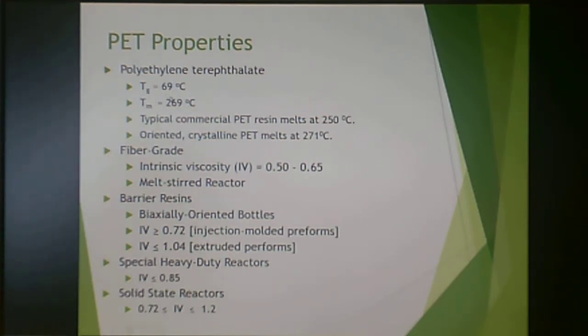69 degrees Celsius is above room temperature, and typically the use temperature of a PET bottle is room temperature or lower. They're refrigerated. So if you blow mold a PET bottle and you quench it, you freeze out the ability for that material to crystallize, and it'll be below its Tg in its use temperature, so it won't have enough degrees of freedom to crystallize while it's in use. So it will remain clear and advantageous for a beverage bottle.